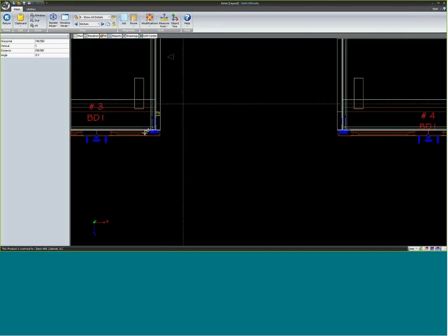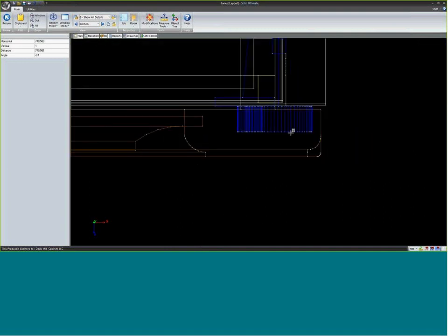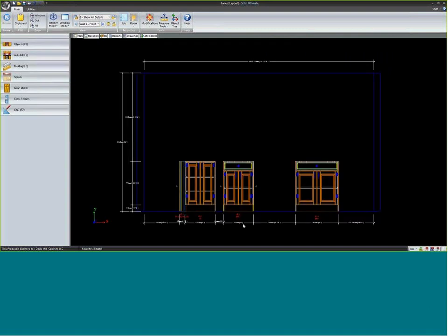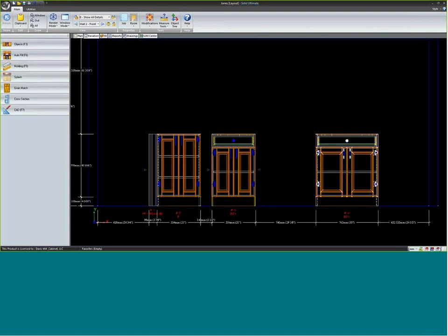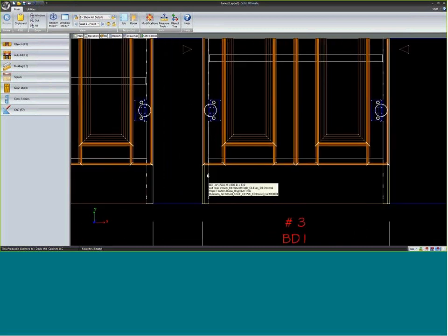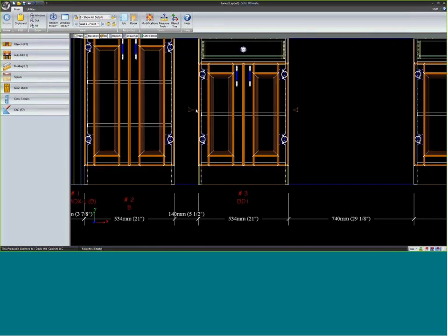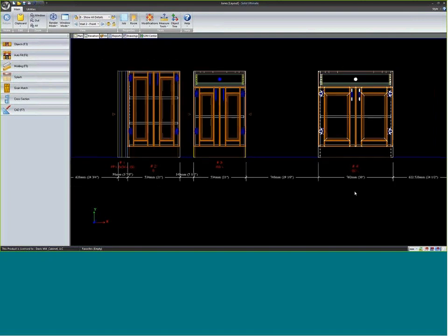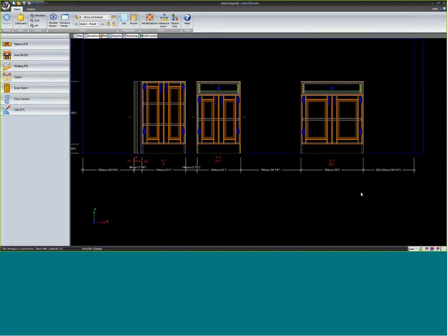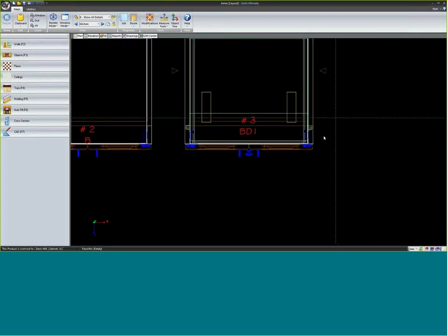The disadvantage of this is there's a lot of snap points on some of these. On Hinge, for instance, you'll see all of these snap points. If I go to my elevation view and turn snap to points on, you only see outside points of cabinets, but I see dowel holes and door profiles and hinge cups and all of those things. Even my finished end arrow here has snap points on it, so you have to be a little careful with that tool.